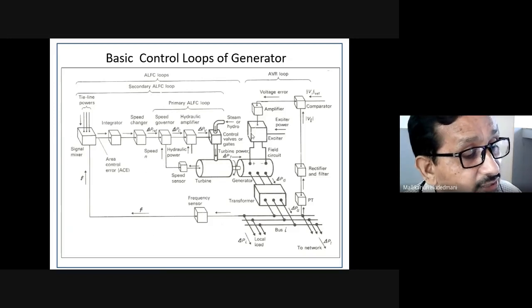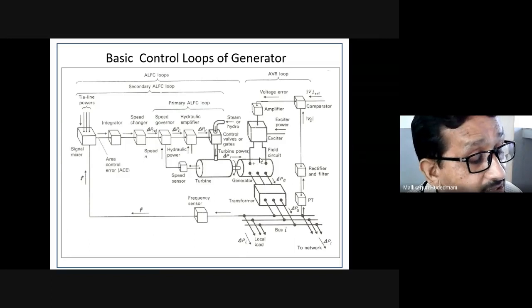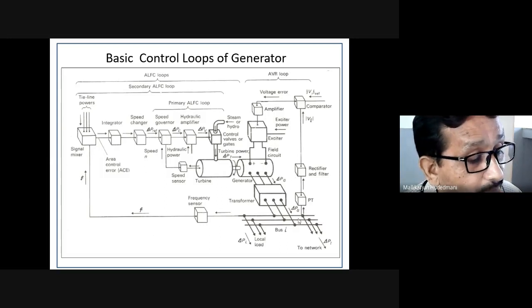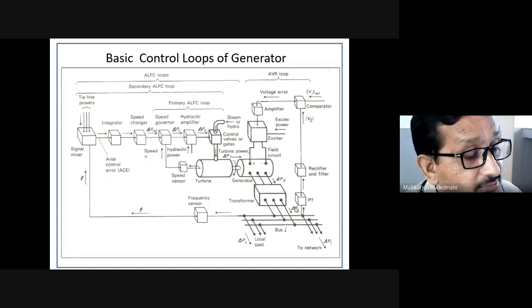For this exciter to control the voltage, whether to increase or decrease it on changes of the load, it has to respond to some stimulus. That stimulus is coming from measurement. You can see here there is a measurement of actual power, rectification of that potential transformer.